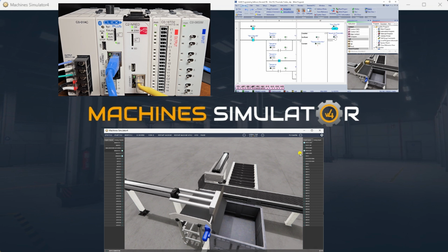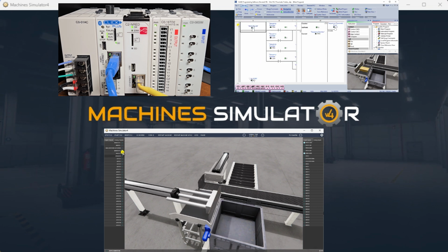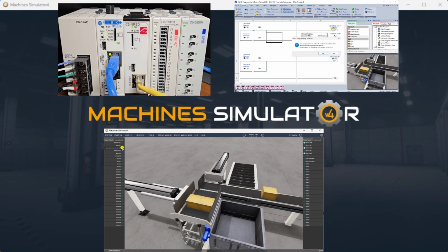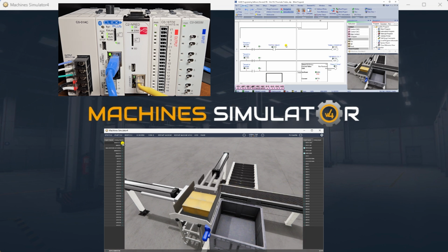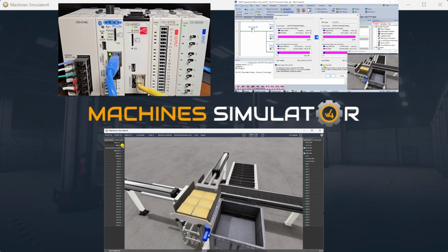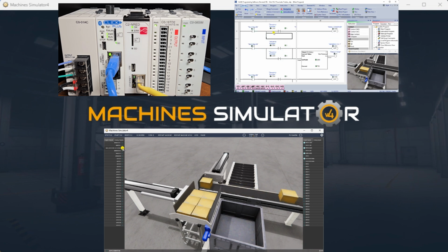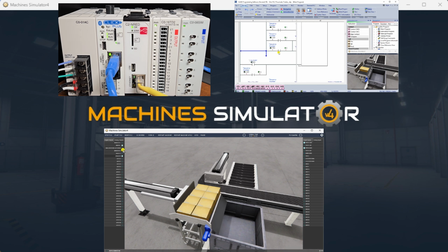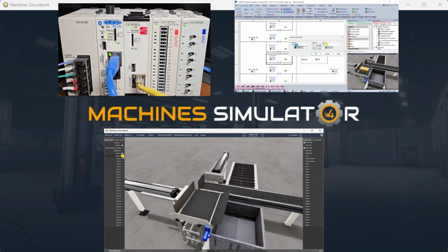A logical sequence of steps will be implemented, with a counter controlling the progression. This fundamental approach to programming sequences applies to all PLCs. We will use the free Click programming software and a Click PLUS PLC to program the Machine Simulator pneumatic pusher simulator. Communication between the software and the PLC will be established using Modbus TCP or Ethernet.